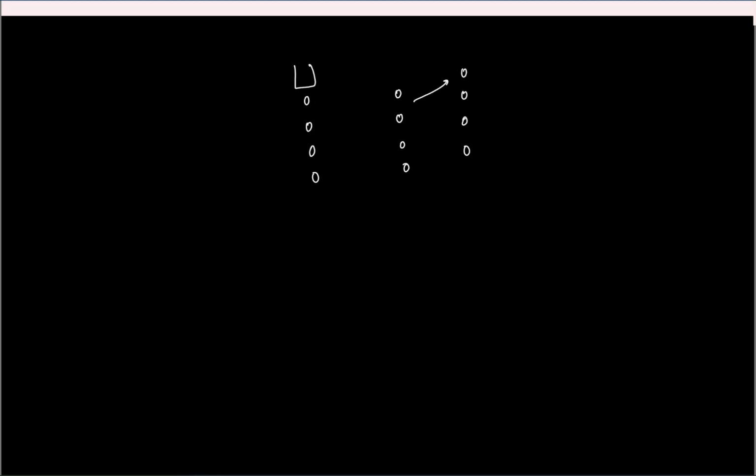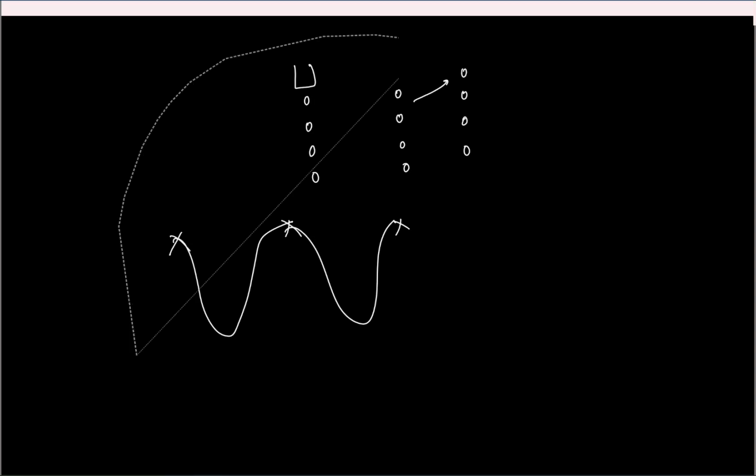The other thing is the fan. If you try to capture the motion of a fan or helicopter rotor using a camera, and the speed of the fan and the frame rate are synced, it will appear as though the fan is not moving at all. Basically, the moment it completes one rotation like this, you take one snapshot here, another snapshot here, another snapshot here. So a fast moving signal will appear as though it's not moving at all. Cool. So that is clear.